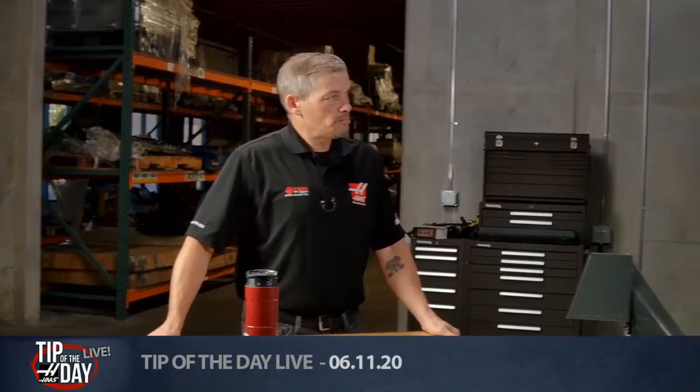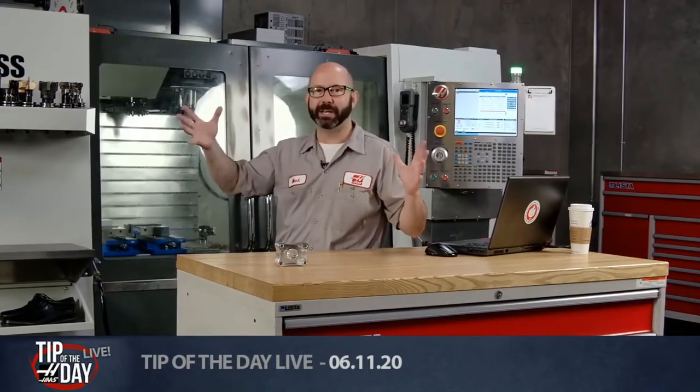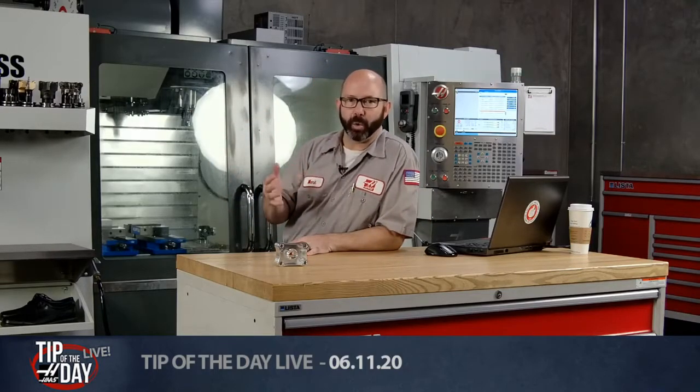So we made this cool thing. So we were just talking about an E value, E as in Edward. Adding an E value to your G00 code if you want to slow something down. If you've got an engine block on a big rotor in your HAAS and you don't want to go in whoosh as it flips between operations, add an E value, it'll rotate more slowly. Now if you add an E value to your G81 drilling cycle, it'll actually spin the chips off of that tool. And we made a video on that, so check out the stringy chips video on the HAAS YouTube site.